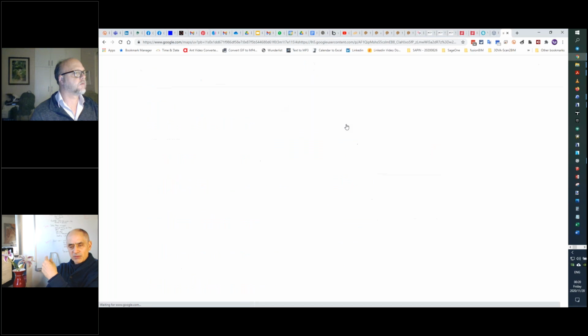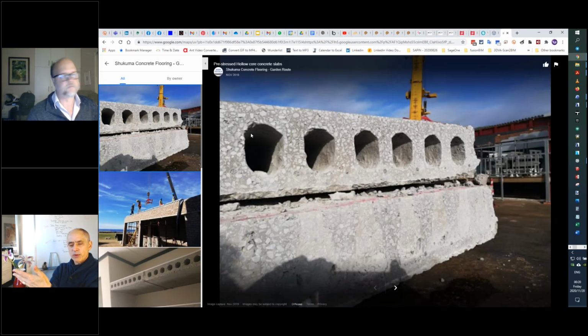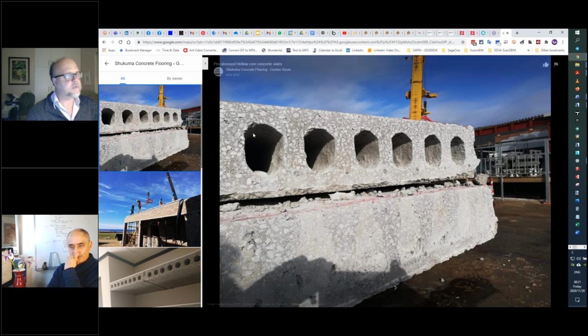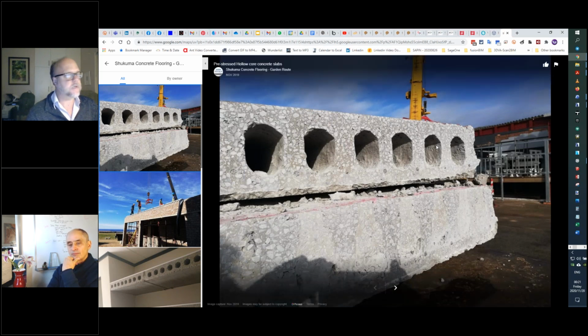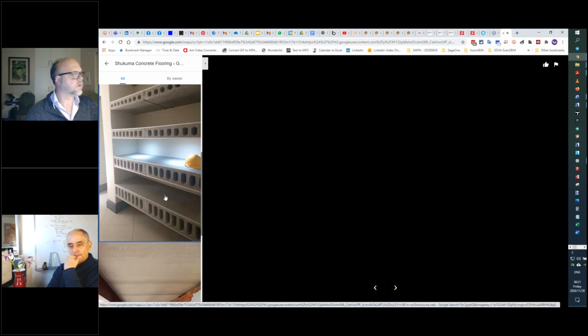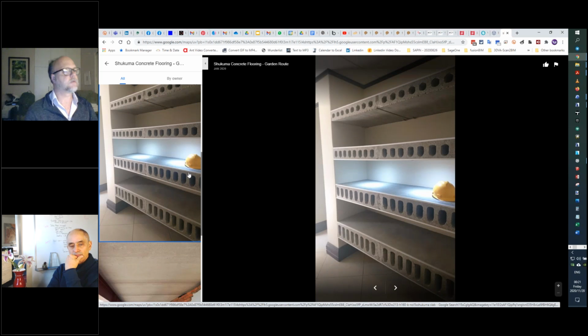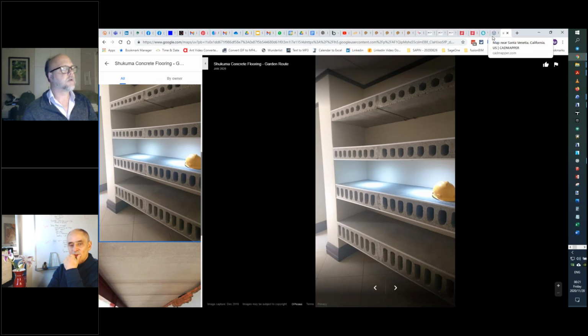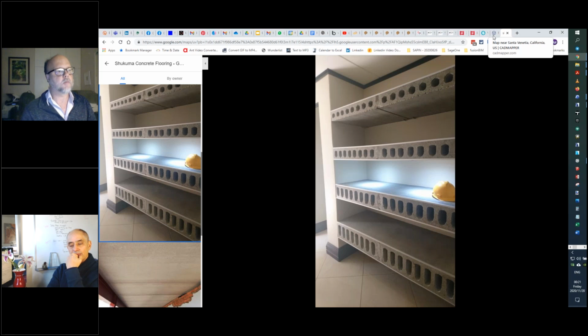And when you do come back to the model, I'd like to see you do a 3D cutaway, so we can see that structure that would relate to that section. Right. I haven't updated the model with the actual geometry of these concrete slabs, but this is a typical photograph of these slabs, what they look like when assembled. Okay, and they get lifted with cranes. The crane that we'll have on this site will have the capacity of an 80-ton lift at a reach distance of 22 meters. So you'll understand, 80 tons at a reach of 22 meters. That's quite a considerable capacity for a crane.